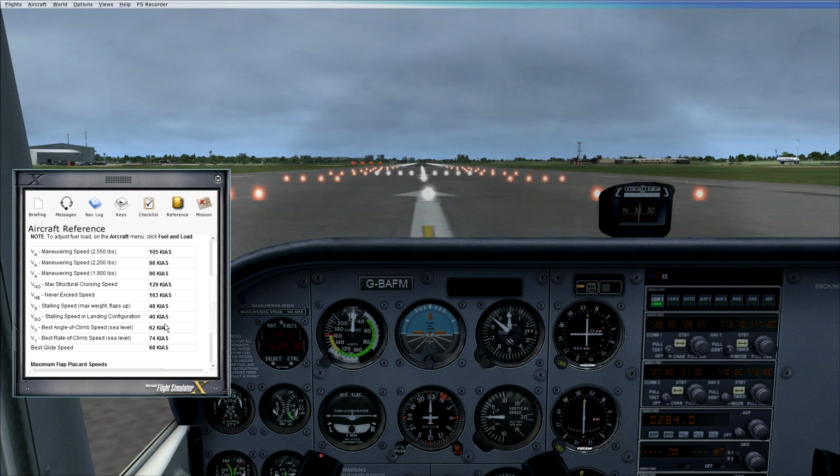Now with the best will in the world, I can't fly precise on this airspeed indicator to plus or minus 1 knot, so I would consider it to be 55 knots as our threshold speed. Now because of the wind, we haven't got much today, but I would consider adding 5 knots. So we're going to fly our approach when we've got everything out at 60 knots, aiming for 55 knots over the threshold. The other speed to consider is the VY, best rate of climb speed.